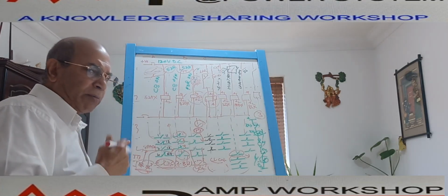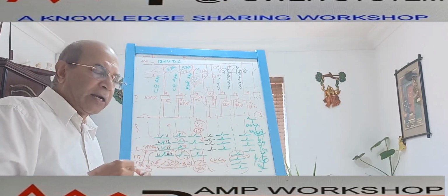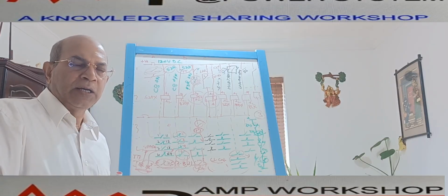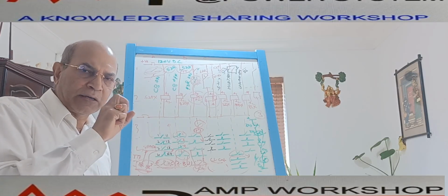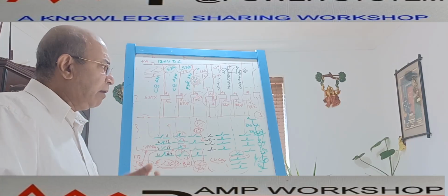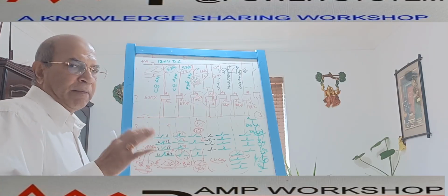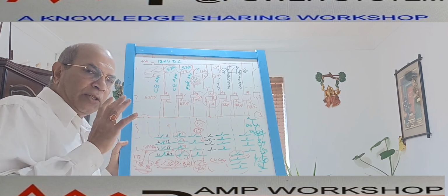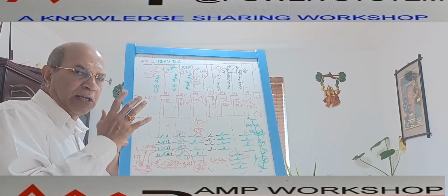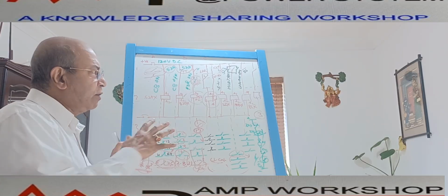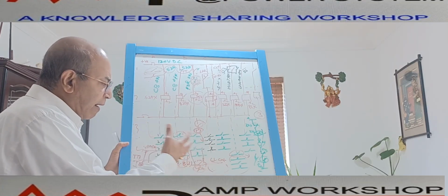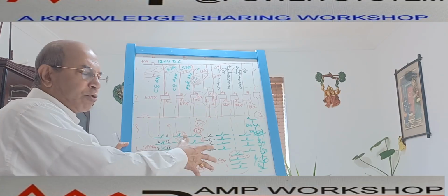So in this way, whatever function we need, if the master device has no multiple contacts for that function, then we take one of the master device contacts and put an auxiliary relay. From that auxiliary relay, we multiply this contact and can use it for various purposes as per our requirement. So this is the auxiliary relay scheme for the circuit breaker control schematics or switchgear control schematics. Why it is required I mentioned, and how it is presented in a drawing and how it can be used, that I have also shown over here.